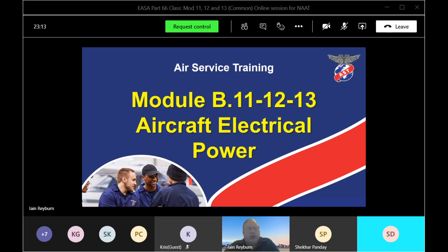Now we're going to talk about something called a latched power contactor. If I look at this basic contactor right now, as soon as I switch on the coil, switch on the current, put 28 volts, it'll go through this coil and that will produce a magnetic field and pull all these contacts to change position. So it would close these contacts and again it would open these contacts.